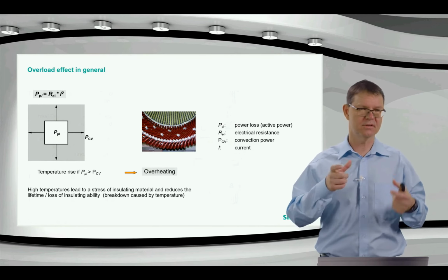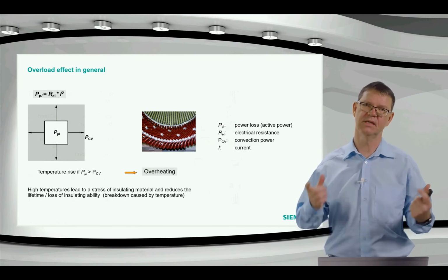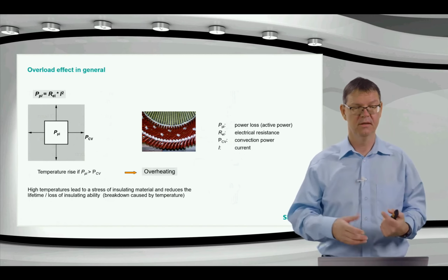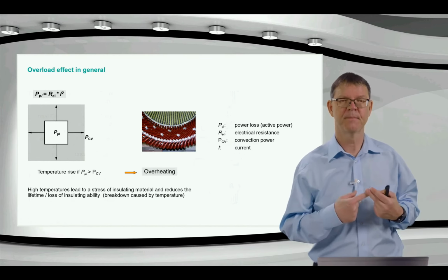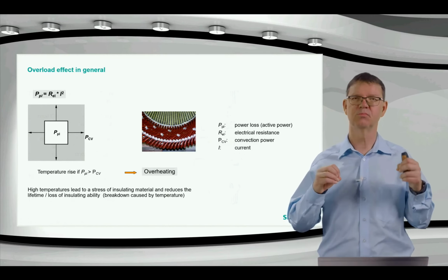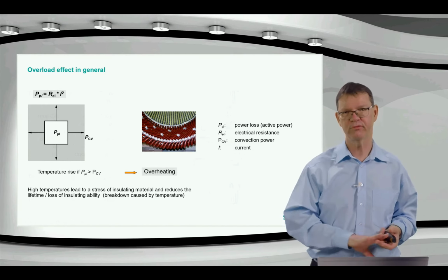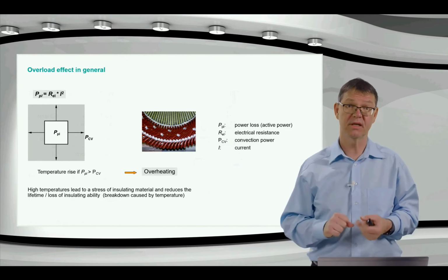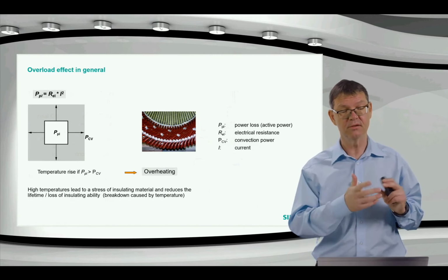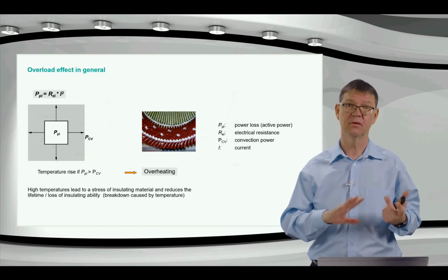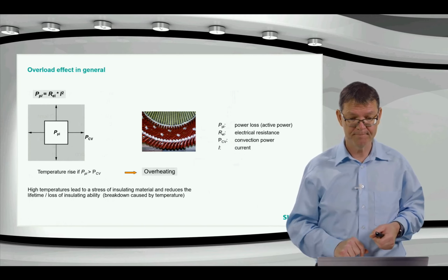I have a resistance inside that represents the iron losses. All that contributes to the power losses. So the motor heats up when a current flows in. The bigger part, however, goes onto the working machine as mechanical power, of course, but there is a rest, and this heats up the motor here.